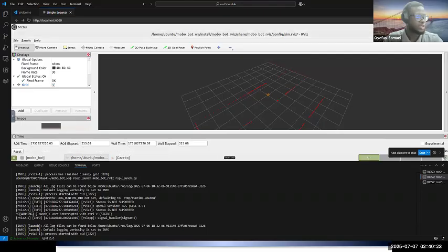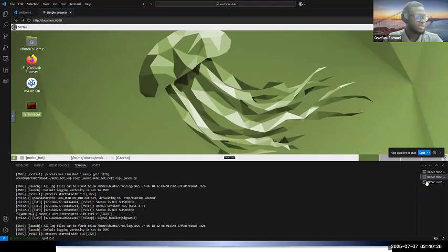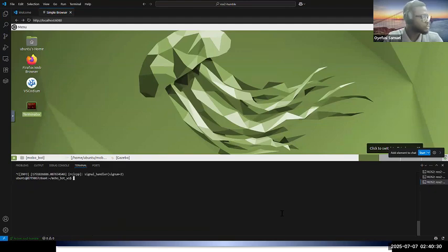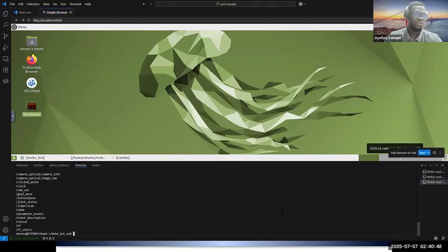We're going to echo the scan topic. The command is simple. What we're going to press is ros2 topic echo /, and the name of the topic is scan. Okay, scan topic now. What can I do is ros2 topic list, because I probably missed the topic name. So we see ros2 topic list. You can see the list of topics. You have cmd_vel. cmd_vel is what we used to drive the robots with the arrow keys.